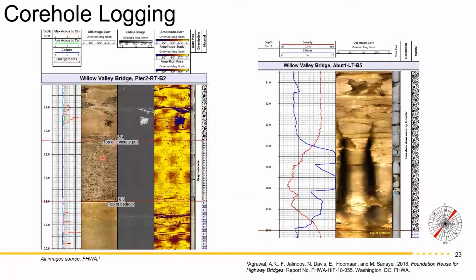Okay, so that's the acoustic televiewer, this one here, and the optical televiewer. Now on the old foundation, we found these very large openings here, which was unexpected, and they were subsequently grouted by our Central Federal Lands Office. So you can see it in the optical televiewer. This is the mechanical caliper. You can see how deep they go. And of course, in the bedrock, you can look at the strikes and dips, and these are rose diagrams. So it's a very effective technology to use for foundations.